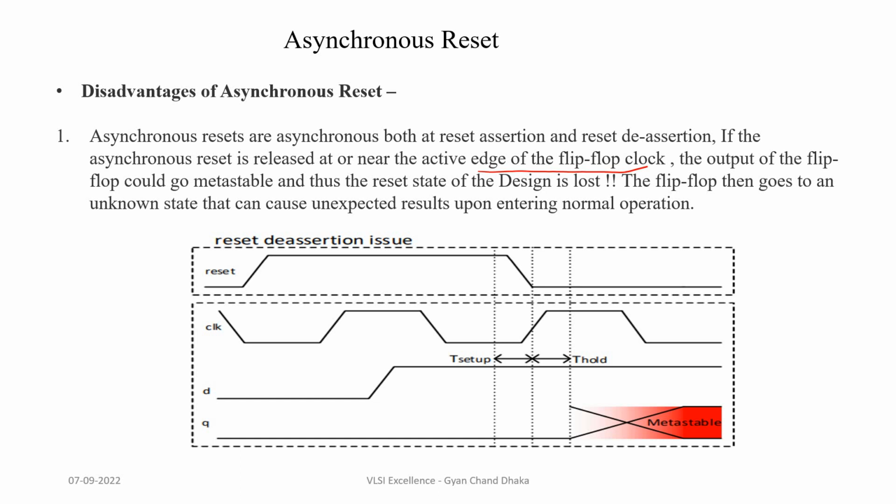Here in this waveform, we have an active reset signal. The active reset signal gets applied here and is released at this point. If you see here, the release is happening at the rising edge of the clock. As we saw in the timing equations when we discussed the setup and hold time of a flip-flop, a similar concept applies to asynchronous timing paths as well, where the reset signal should be stable before and after the clock edge for some time.